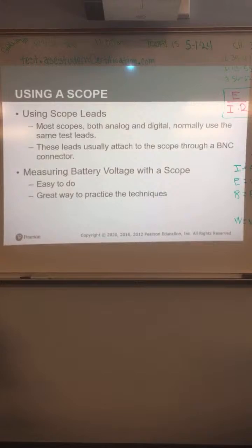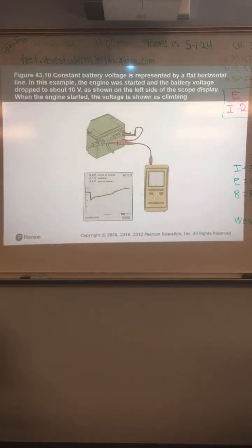Scope leads, nothing really to see there. Most have both analog and digital. Normally use the same test leads. Measuring battery voltage with a scope is very easy to do, a great way to practice the techniques.